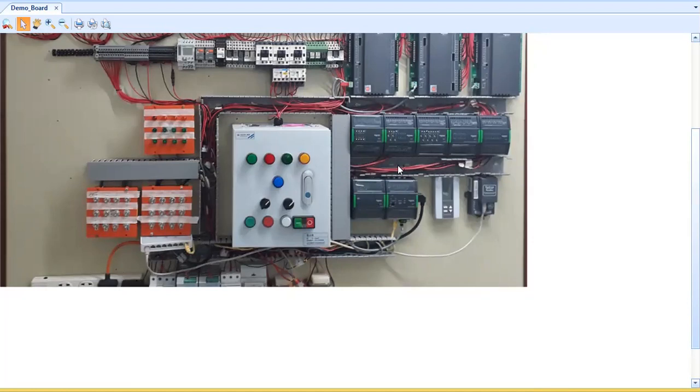Actually, you can have several automation servers that will handle several areas. Those automation servers will be connected to your network switch using Cat6 cable and the TCP/IP communication protocol. I hope you get the idea, or you get the answer to your question.